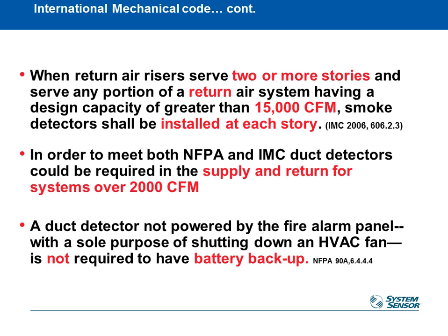We do get a lot of questions about whether the duct detector needs to be powered off of the UPS backup power system, because many of you know that the fire alarm systems generally are on the UPS. The duct detector does not have to be powered up on the UPS if its whole job in life is to just shut down the HVAC fan. Then it does not have to do it. So if the duct detector is getting power from the same exact power source as the HVAC fan, and its job is to just shut it down, you don't have to put it on backup power.